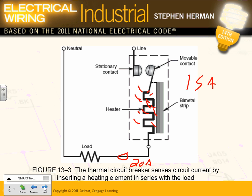As the heat starts coming out, guys, here it heats this material. When this material heats at different rates, it will move. Can you guys see that contact? It will move that little deal here, and it pushes the contact to open. When the contact opens, it interrupts the flow of that 20 amps that's going through the circuit. So heating, 2 dissimilar materials.